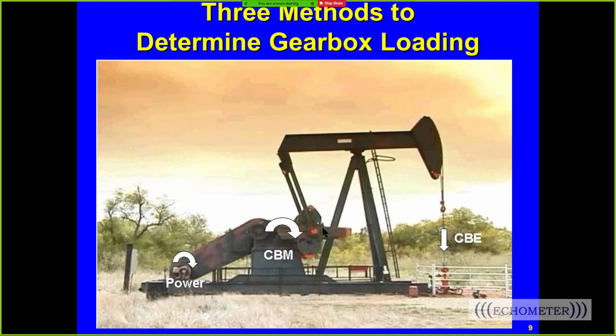That then becomes inches from the gearbox shaft center, inches from here to the center of gravity, and we take that distance times those inches based on the inches you tell us from end of crank, and we sum all that up, and that gives us the moment. Then the moment, along with the dynamometer card and the torque factors, become the net torque.